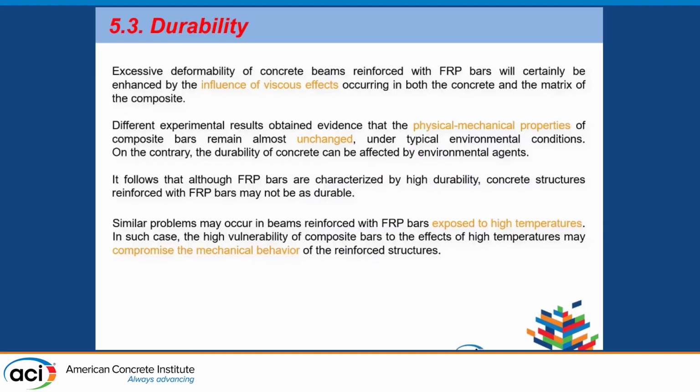Regarding the rebar, I would say that the results available in the literature show that their mechanical behavior is not significantly affected by some of the more common environmental agents. However, the same is not true for the concrete. So, although FRP rebar are characterized by high durability, concrete structures reinforced with FRP rebar may not be as durable.